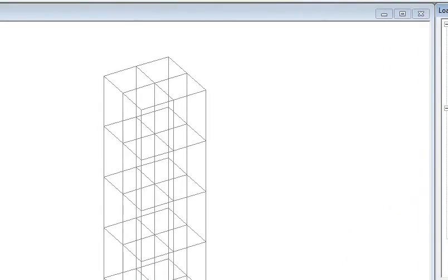Now we have already created the various load case details. The next step in the wind definition is different from the dead load and live load: go and create the wind definitions. That is, we are defining the way in which the wind will be acting, because the wind acts in various ways in various parts. Say in a coastal region the wind intensity is a little higher.